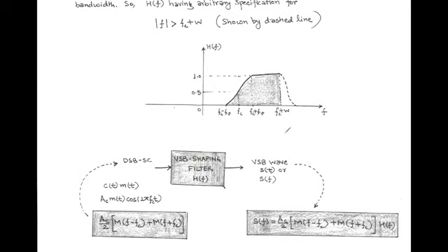So with the help of this specially designed sideband shaping filter, we obtain the vestigial sideband from the double sideband suppressed carrier wave. Here the double sideband suppressed carrier wave is given by Ac cos(2 pi fc t) times m(t) in time domain, and in frequency domain it is given as Ac upon 2 within bracket M(f minus fc) plus M(f plus fc).